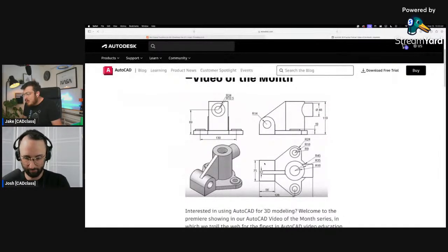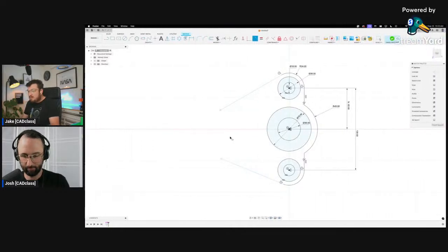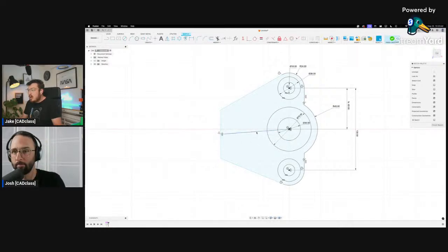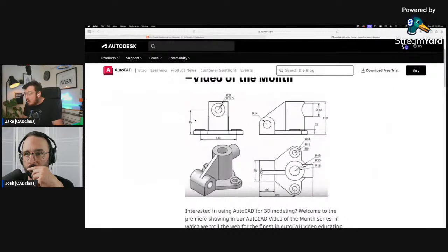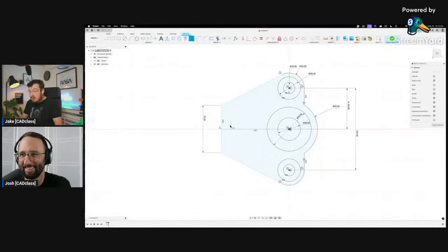What is that? 56. That's 75. Okay. So I'm going to join these 2, make that totally horizontal. I'm going to be making a midpoint to the origin. That's going to be a construction line that is also horizontal, which is going to be pulling it up as well. Pull that away. Did I say 75? 75 for that. Let me check. Lovely. So the distance between... Oh, for God's sake. I'm just going to be adding on a construction rectangle from that point just to match that dome.